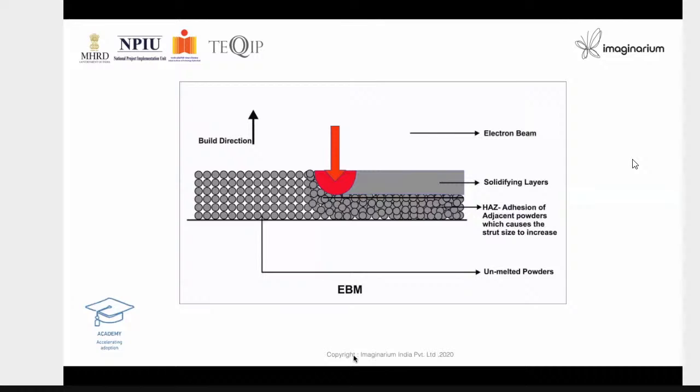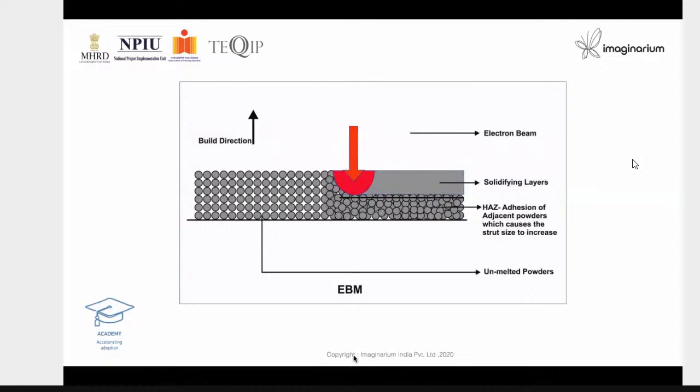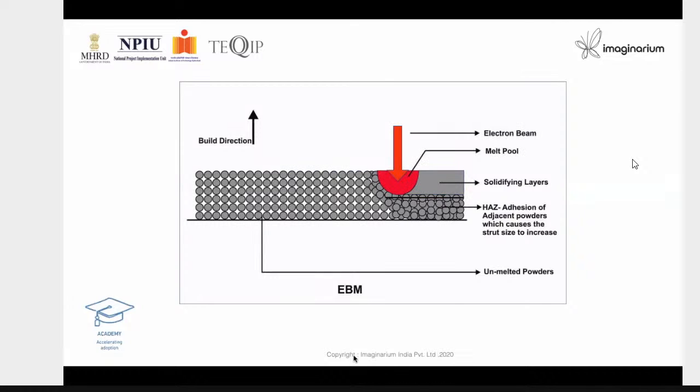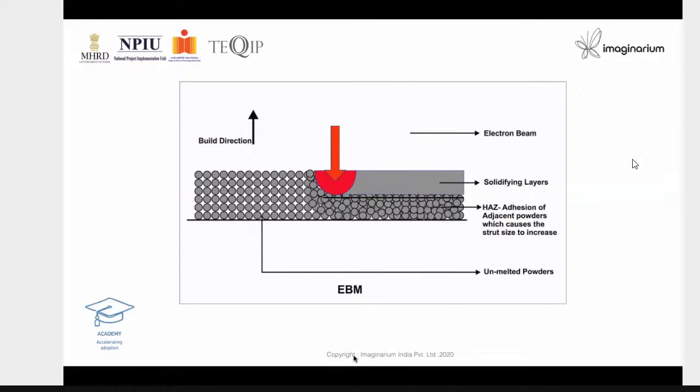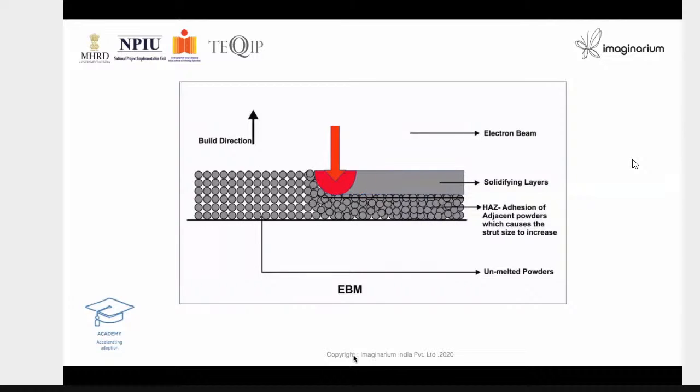So 3D printed, though it uses powder like SLS, in metal printing we always have a support for two reasons: to anchor it to the substratum, otherwise the part will move, because it has got a different specific gravity, and it can move because of the inertia also. As the table moves, this also moves. The powder density and the finished part density are different, so it becomes like two different bodies.